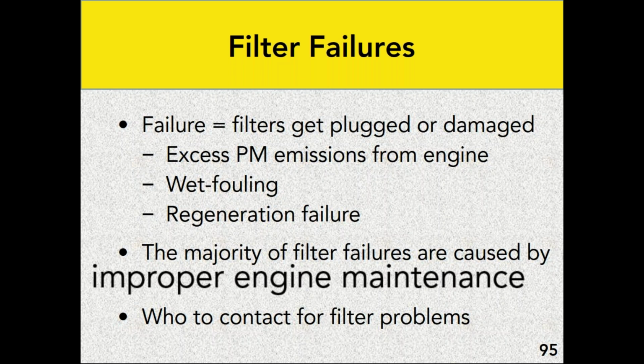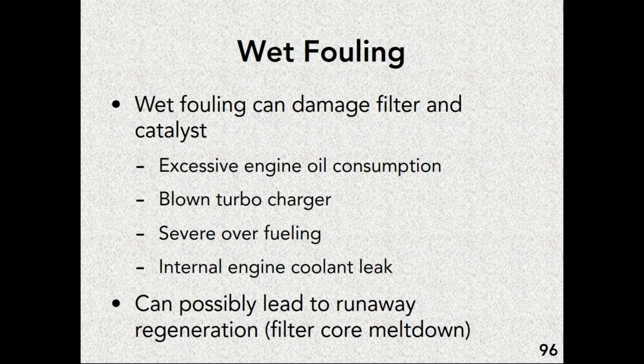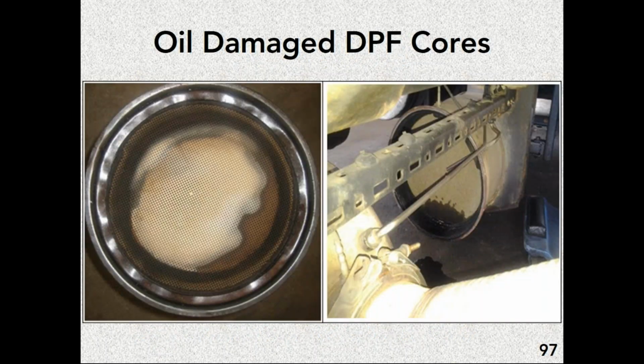Wet fouling is simply put having too much liquid deposited on the filter itself. That could be from excessive engine oil, from severe overfueling where raw gas is just shot onto the filter. It'll happen whenever a turbocharger blows, whenever there's an internal engine coolant leak, and it can possibly lead to a runaway regeneration. Here's a couple of examples of oil deposit on cores.